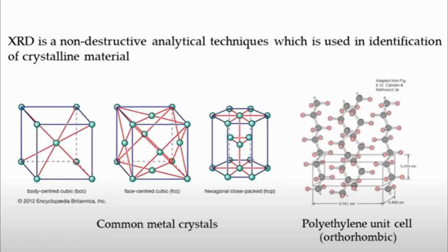As food for thought, you can go back today and think about how this crystallization happens, how these lattice patterns are designed, and what their internal architecture is like. And why are crystals important? Because once a crystal forms, its patterns are very symmetrical, meaning the repetitions are identical. So if anything has a repetitive structure, the complex structure can be narrowed down to a unit structure, that is a unit cell. If you keep repeating the study on this unit cell, you complete the entire structure. That is the beauty of a crystal, which is not possible with amorphous or other types of material. That is why crystallography and forming of crystals is so crucial, because it gives you not only a fixed orientation but a repetitive one, and you can break it down into a smaller unit cell.